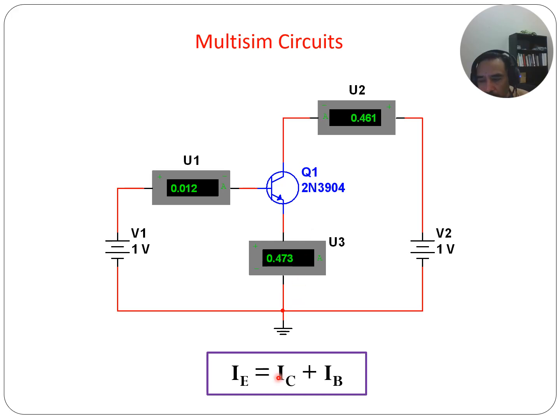And to simplify things, always know that the emitter current, which is definitely down here, and the collector current, they're going to be very close, almost the same. So if you needed to do some kind of quick calculation just to get an approximation, you know that when it's conducting, these two need to be almost the same thing. So we do these shortcuts once in a while just to get an idea of what to expect instead of running through these whole calculations.